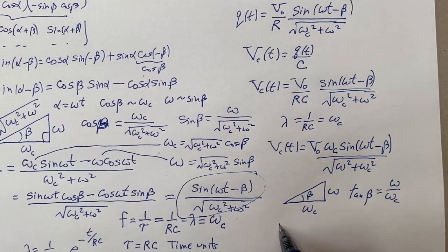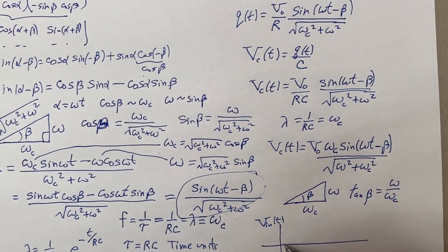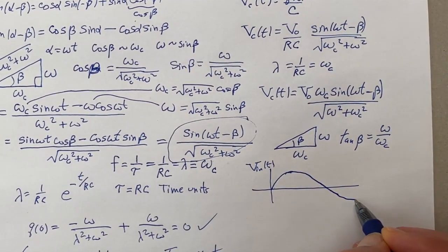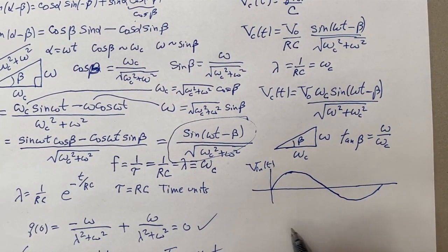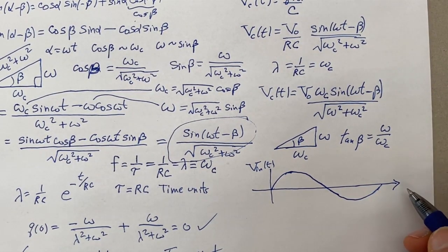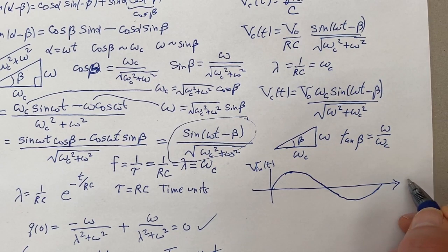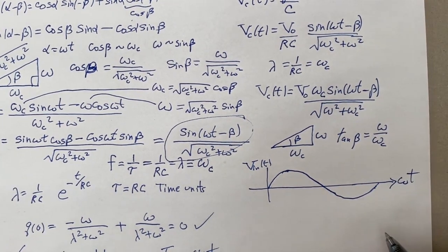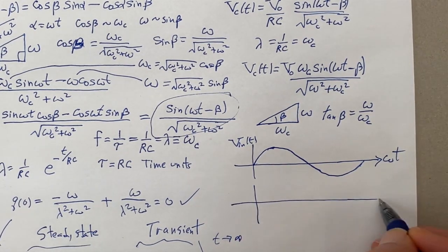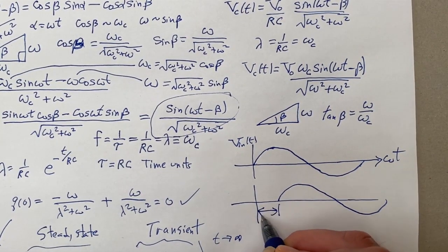And if we were to do a little plot, say, of the incoming function, which is a sine wave, something like this, right? Then what about this with the minus sign? Well, we know that if this is the angle, let's just say we're looking at omega t here, we're plotting the omega t, and if you have the minus b, that means you're going to shift this thing to the right. We have looked at that before, where that would be beta.